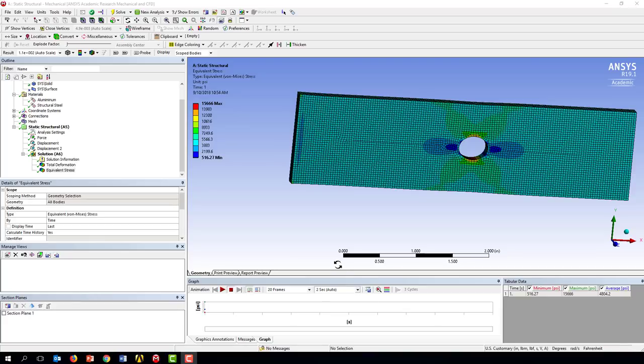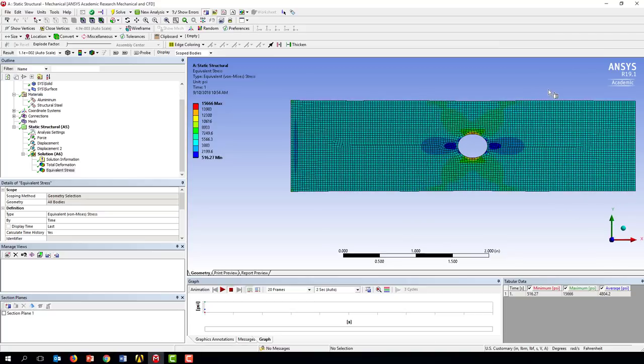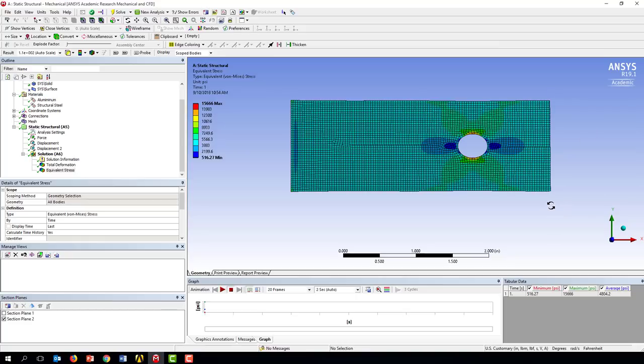And in this clip, I want to show you a little bit about how to both tune your mesh and to inspect your mesh. One of the tools you have available here is up here at the top for the section planes. And you can see down here I have a toolbar that says section planes. And I can come in, and let's orient normal to this, and I can draw a line. It's going to draw this relative to whatever face we have. And it's not perfectly straight, but that's going to be all right.